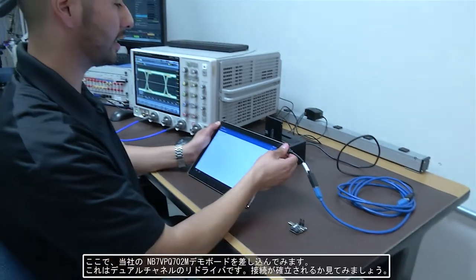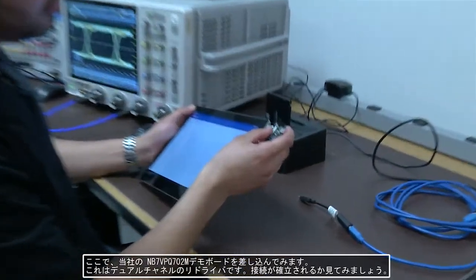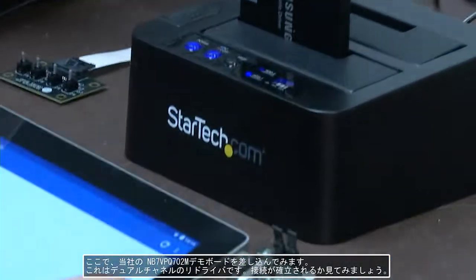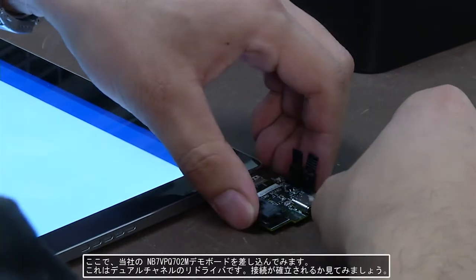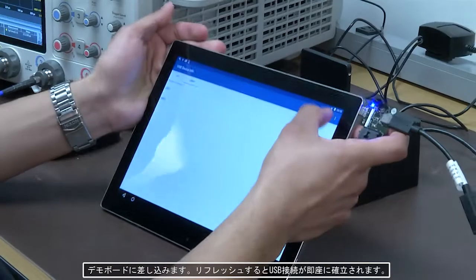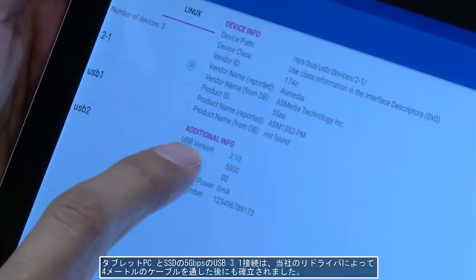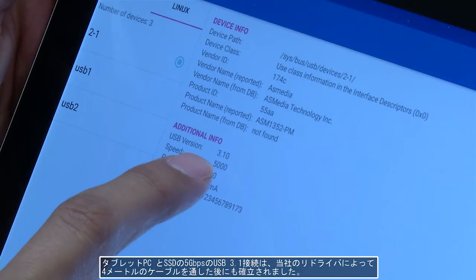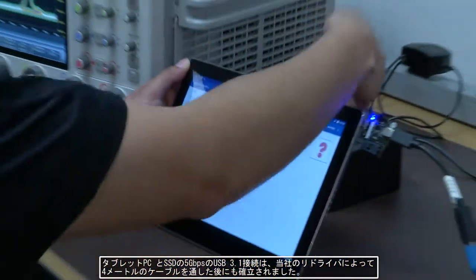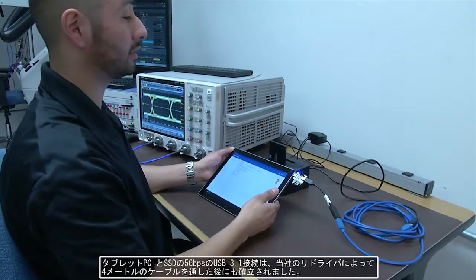Now let's plug in our NB7VPQ702M demo board, which is our dual channel redriver, and see if we can establish a connection. Plug in our demo board, refresh, and immediately you see a USB connection pop up. A USB 3.1, 5 gigabit per second connection between the tablet and the solid-state drive was made with our redriver and 4 meters of cable in the system.